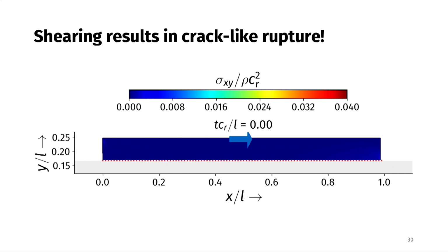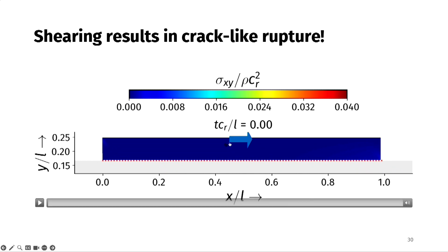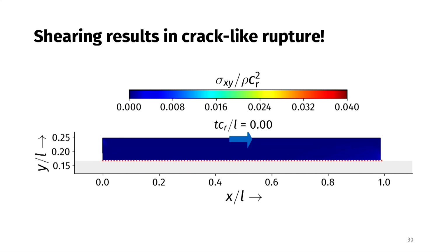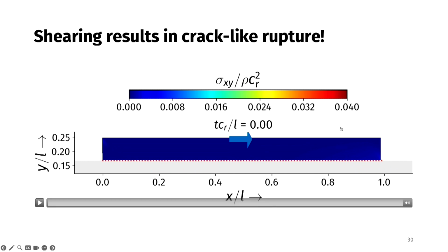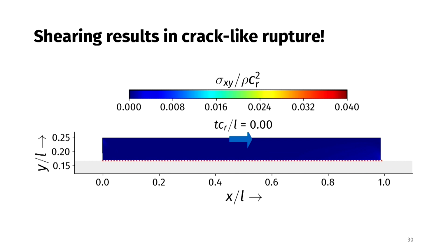Okay, now here is where things become very strange. Remember, we had these two waves going in the same direction, detachment, and so on. Now what happens if you shear it from the top? If you shear it from the top, there are two things. One is this shearing is basically what you do in mode 2 fracture. It's the same configuration. There is an applied load, here an applied velocity, but that difference notwithstanding, the configuration is the same as what is described in classical Westergaard solutions.